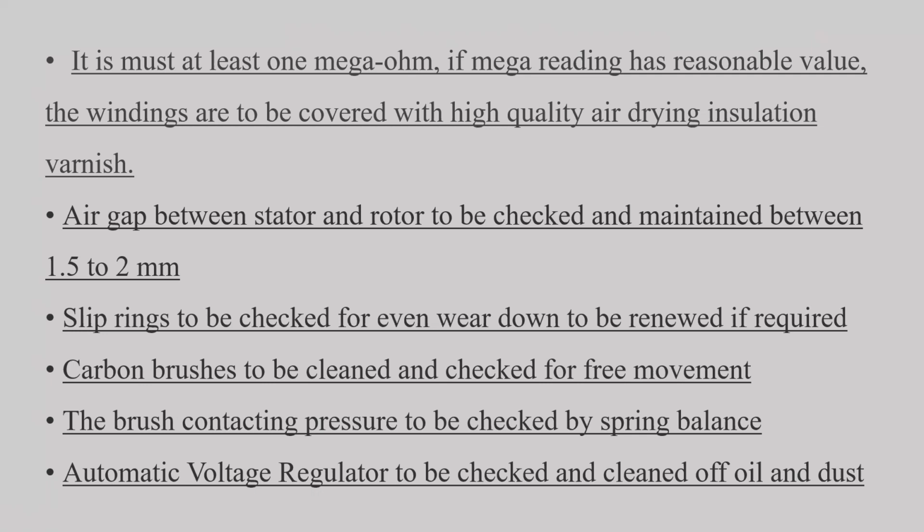And next, the air gap between the stator and the rotor is to be checked and maintained between 1.5 to 2 mm. For suppose an induction motor, there should be a proper air gap. Induction motor is a self-starting machine. Because of the air gap, it becomes a self-starting machine. There is always a relative speed difference between the stator's rotating magnetic field and the rotor. So this air gap is very important, that we have to maintain it at 1.5 to 2 mm.